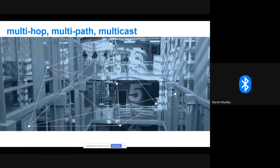A device that wants to communicate with one or more other devices somewhere in the network, and they may be quite some distance away in a very large building or maybe even in another building, will send a message. And that message will find its way to its destinations by hopping across the network from device to device to device. Now, we allow up to 127 hops, and the range that a single hop can cover is probably in the order of over 100 meters. Bluetooth Low Energy today has a range of certainly hundreds of meters. In the context of a building, it will be less.